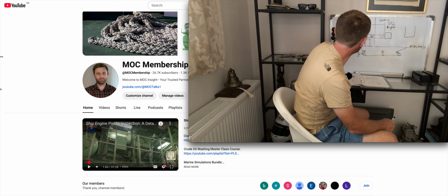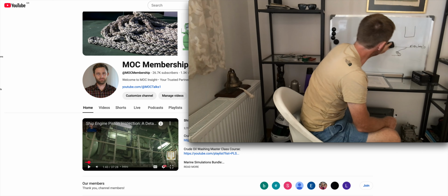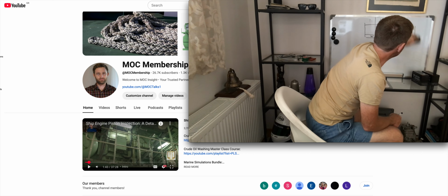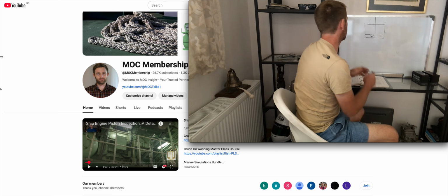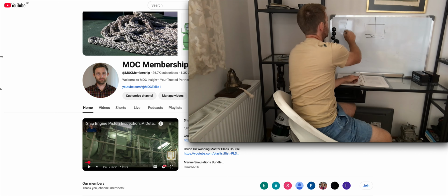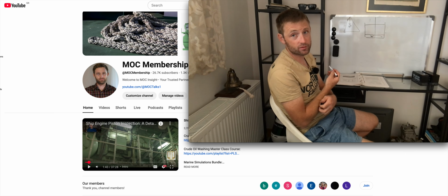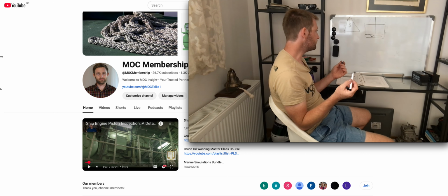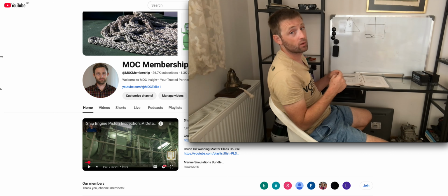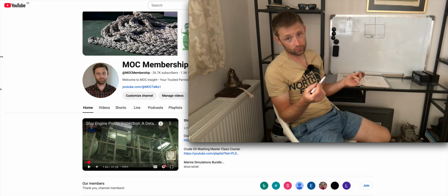But at this point, what is important is to have the list at 0. So we will also check the clinometer, which is located in the ship's office. We check that it is 0. Because sometimes you see there is a small list, let's say to the right or to the left, but most of the cargo surveyors will not do this correction, okay? They will take it as 0.